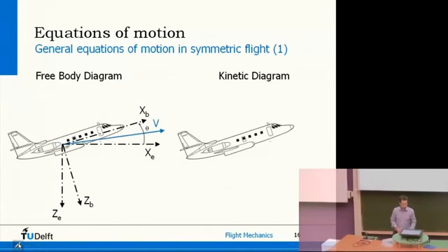Now the aircraft isn't following its nose, so you have a certain airspeed, and that is in a different direction than the nose of the aircraft. But the airspeed vector, of course, is very important, because this one determines where you're going, and that is very relevant from a performance point of view. We can also define the angle between the horizon and this airspeed vector.